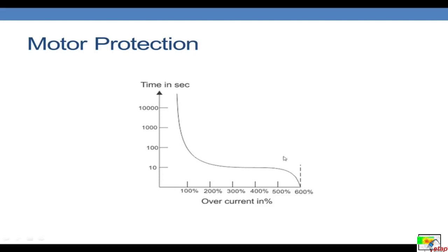So over here I have the motor curve, which is the TCC curve. As you can see from the curve, at the initial condition, that is at 100% of slip, the current drawn by the motor is likely 600% of its full load current. At a particular instant this current reduces, and when the slip becomes say 3 to about 5% of slip, you can see that the full load current appears across the motor. So motors are somewhat different from your existing lump loads due to these characteristics.